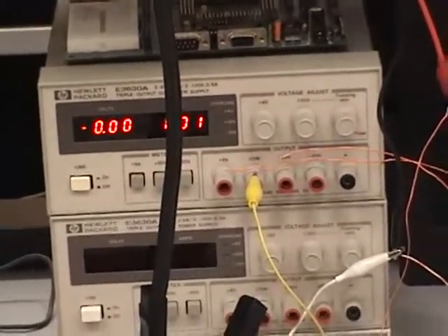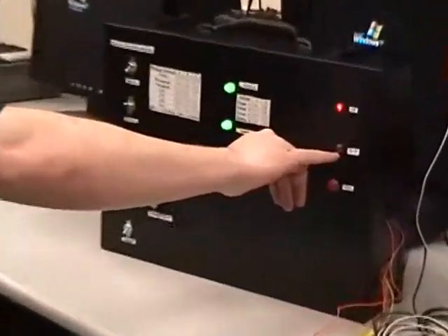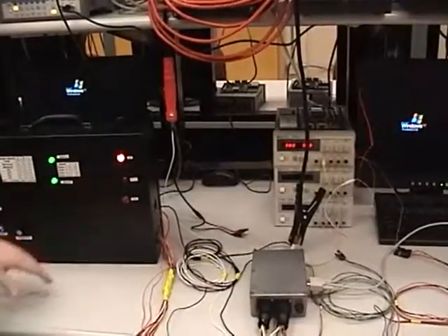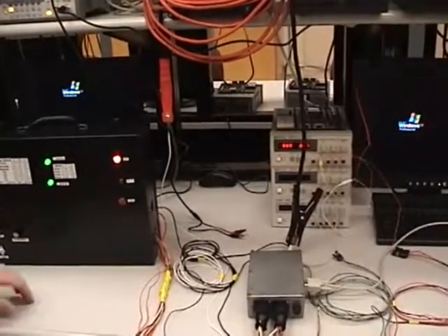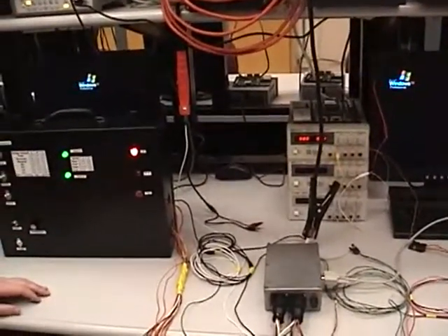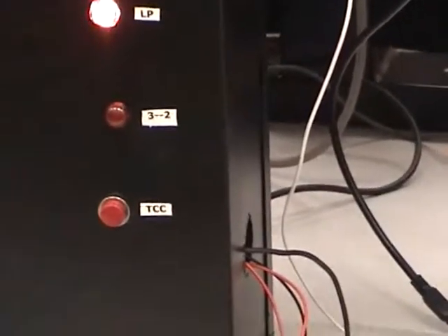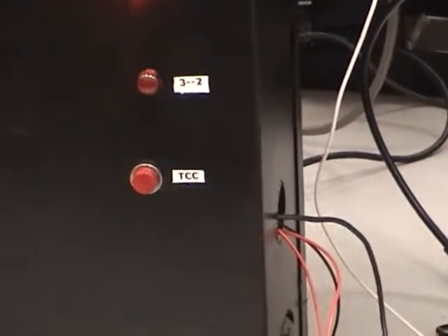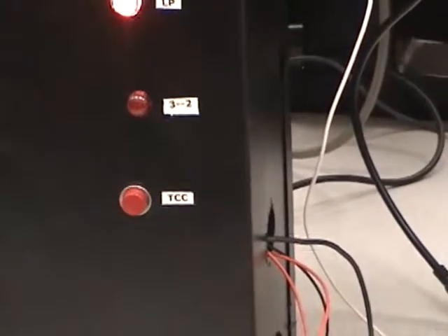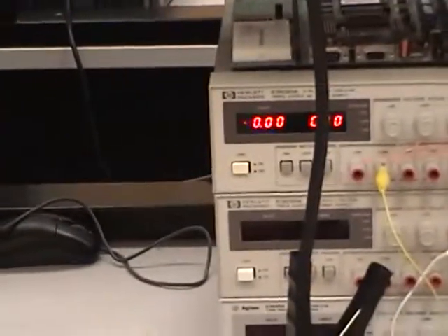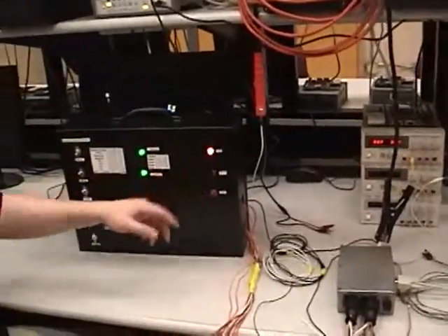This right here is another pulse width modulated solenoid, your 3 to 2 downshift solenoid. This is normally 10% duty cycle, which you can see right now. It probably doesn't show up on the video, but it has a faint glow to it. And anytime it's not in first gear, it'll go to 90%, so it'll be in its brightest state in 2, 3, and 4. This is to cushion the downshift from 3rd gear to 2nd gear due to someone pushing on the throttle really hard and making it do that downshift. It's to let the engine adjust to the new RPMs that are going to be in second gear.